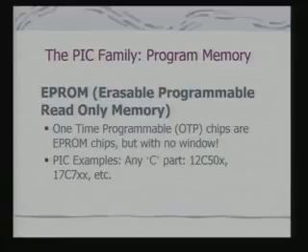One possibility that we have seen already in the diagram is EPROM, erasable programmable read-only memory. In fact, one-time programmable chips are EPROM, that means they have EPROM but there are no windows. Why no windows? Because I can use the window to erase a program through ultraviolet light, and if there are no windows, then effectively I cannot erase it. So I get one-time programmable. In fact, they are something like a factory programmable chip.